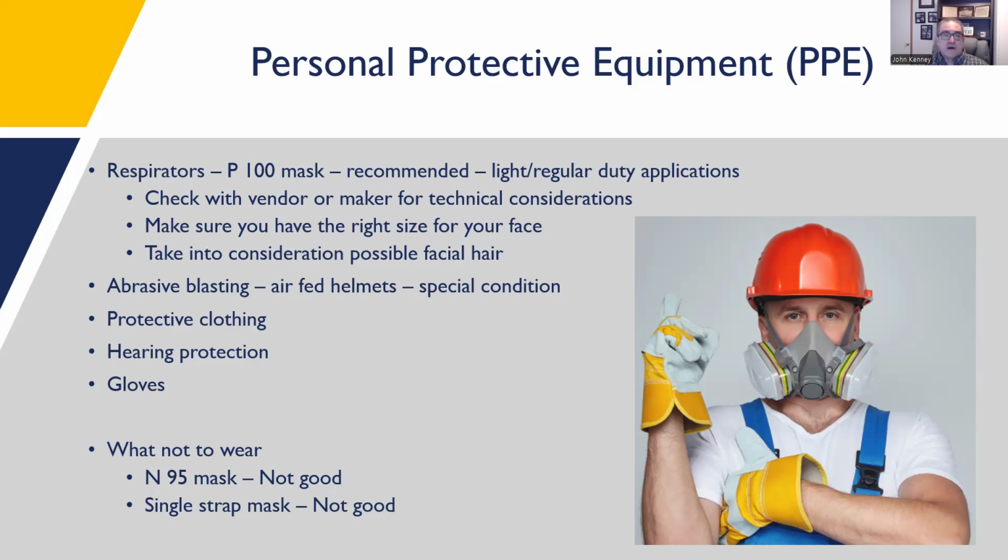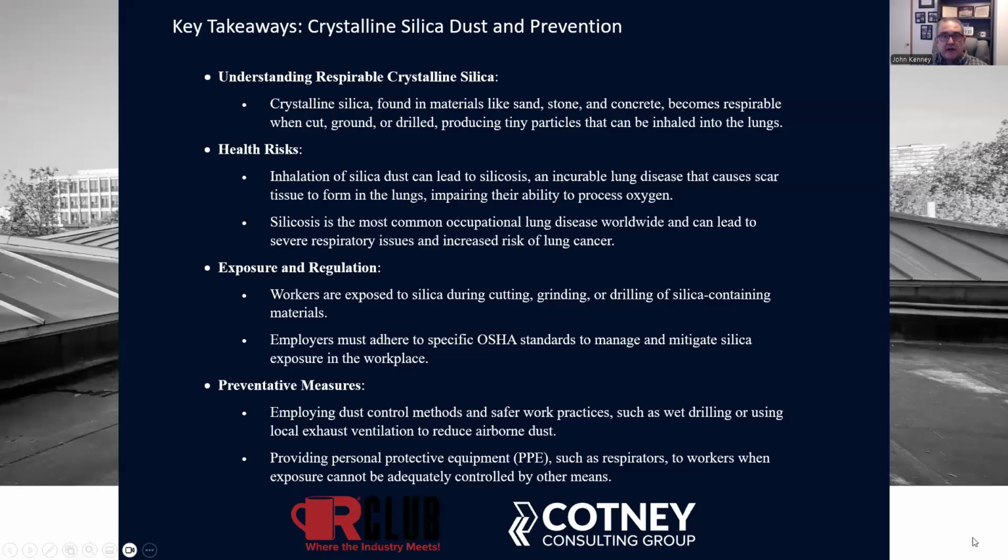Abrasive blasting, air-fed helmets, a special condition. Unless you are actually doing abrasive blasting on surfaces, which you may be if you're waterproofing. So depending on the type of work is what you're going to need for equipment. Protective clothing, hearing protection, and gloves. What not to wear. N95 masks are not good. Other simple masks that we use for prevention will not work. Single strap masks cannot be used. They must be double strapped. Again, use the right mask for the right situation.